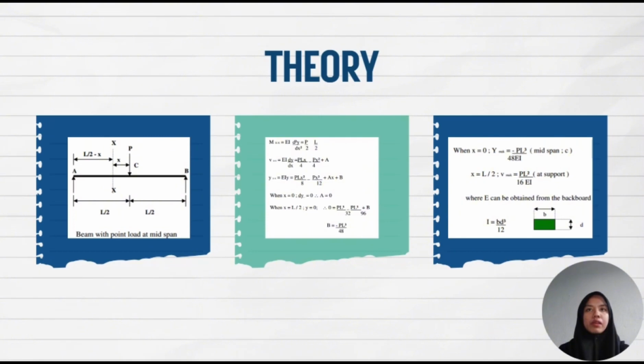Thirdly, determine the bending moment using loading and support conditions. Fourthly, substitute bending moment into the integrated equation to find the deflection. Lastly, in a lab, measure deflections under known loads and compare with theoretical predictions. By comparing theory with experiment, the double integration method's accuracy and the beam's behavior can be assessed.